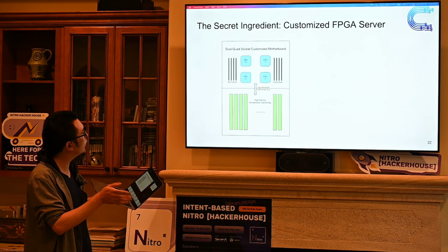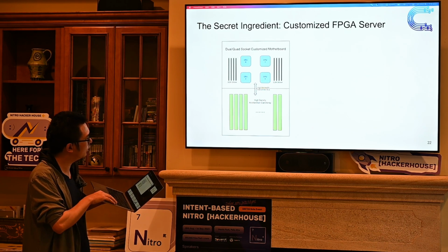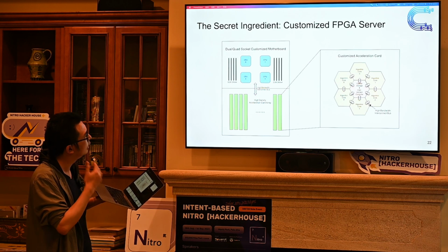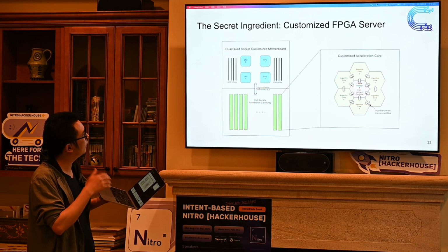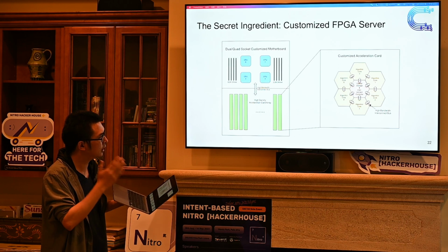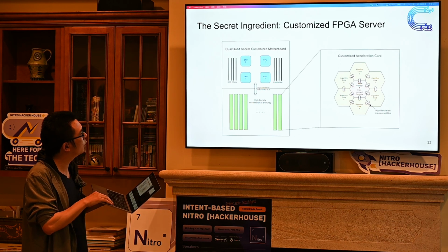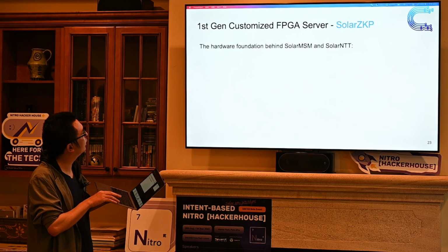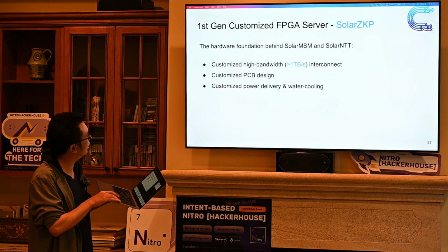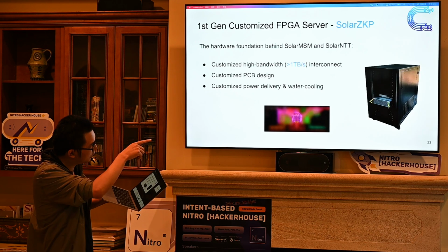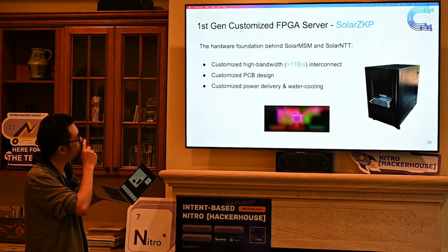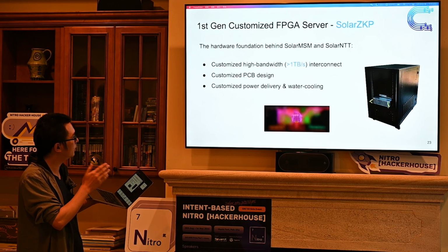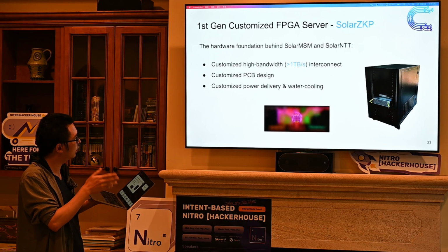All the performance we show here is not from a single FPGA die. It actually comes from our FPGA server, which can have multiple accelerator cards, each card with several processing elements on it, and this is how it looks: a huge machine with customized high bandwidth interconnect, customized PCB design, customized power delivery and water cooling.